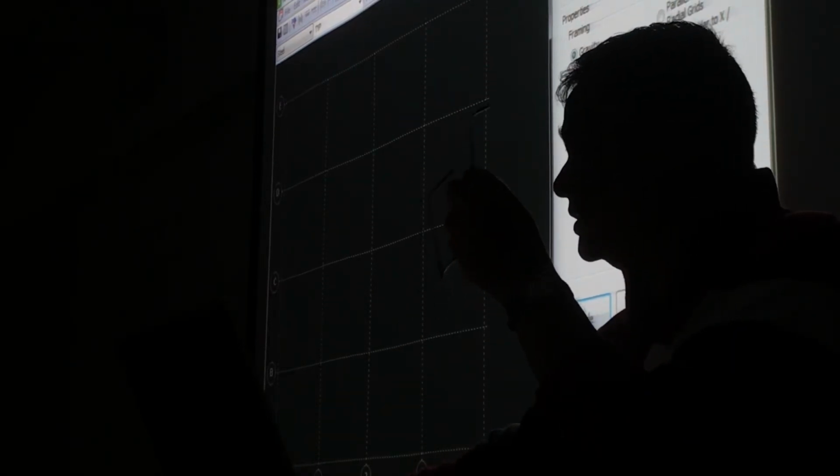Usually, I'm going to use a white plain section. I do not know the size yet, but we will learn it, or we will design it. At the beginning, I will say that let's start with gravity framing. At the level of moment frames and brace frames, those will be lateral. But we can always change the property. Geometry is I section.